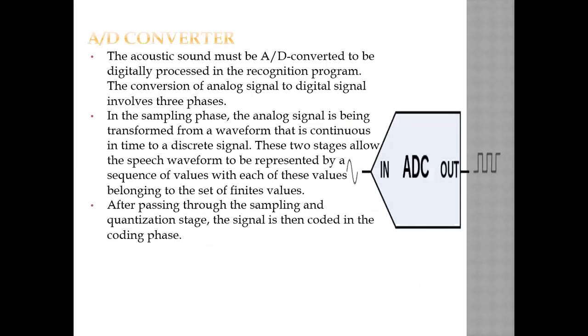So this is very, very important: the A to D converter. People may think simply that the A to D converter is a very, very simple topic. But if you look at the conversion process, because I give analog input, I expect a digital output. Between this is a conversion process. This processing time should be minimal so that I am able to get the digital output earlier. Because if the processing time is lengthier, what will happen is the analog signal changes within the time of delta.